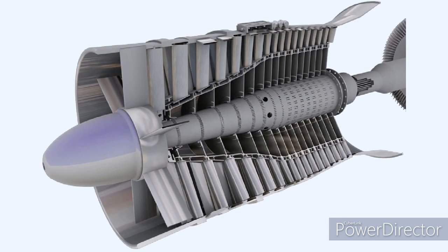In some engines at low compressor RPM, the relationship between RPM and airflow axial velocity may not be maintained to give the rotor blades the optimum angle of attack, unless some of the excess volume of air is allowed to escape from the intermediate stages of the compressor. If a compressor bleed valve, like the one shown here, is fitted to the compressor casing at a position adjacent to the intermediate stages of the compressor, it can be opened at low RPM and during engine acceleration to allow some of the excess volume of air to escape.